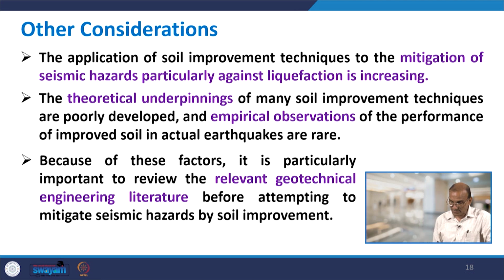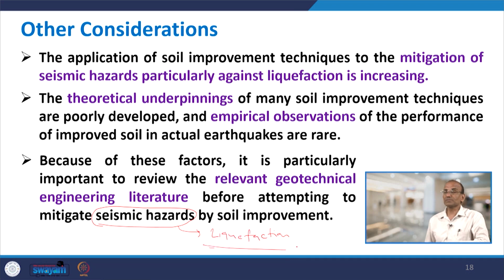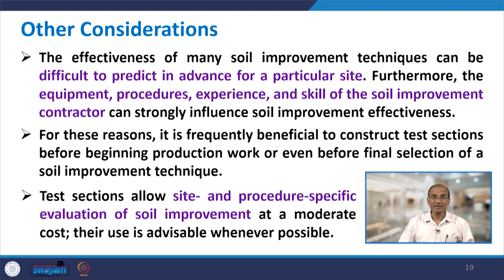For example, one of the seismic hazards we deal with is liquefaction, and when you improve the soil, your objective is not simply to increase the shear strength, but in many cases to mitigate liquefaction, or you can say to increase the liquefaction resistance of the soil. The effectiveness of many soil improvement techniques can be difficult to predict in advance for a particular site. Furthermore, the equipment, procedure, experience and skill of the soil improvement contractor can strongly influence the soil improvement effectiveness.